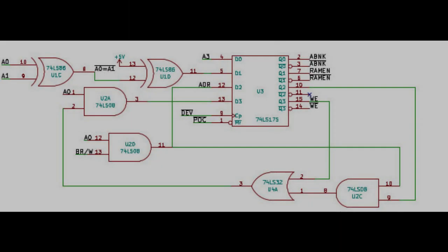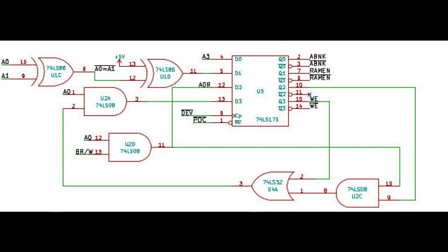The configuration bit part of my schematic is actually a gate-by-gate replica of the original language card, except that on the first revision of my PCB I thought I could spare one gate with respect to the original schematic. But I realized soon after ordering the first PCB that this optimization would actually cause the Apple II not to start with my board, because the gate was really needed to allow the ROM to be selected at power on. With my so-called optimization, the RAM would be selected at power on, and the machine would never start because the RAM content would be random at power on, of course.